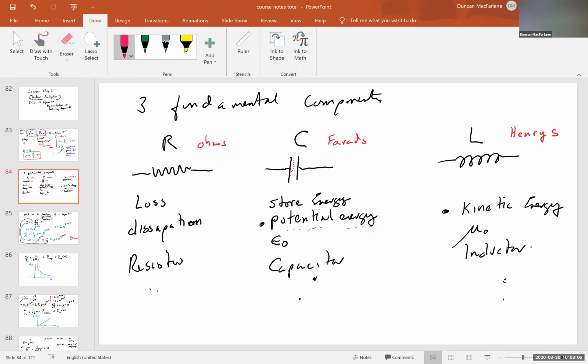So sometimes if you're building a circuit, you talk about parasitics, or you're building a device that is working with the electrics and the magnetics of the situation, and you'll throw in parasitic resistances, capacitances, and inductance so that you can best design and best understand those situations, those effects. So again, always associate resistance with a loss.